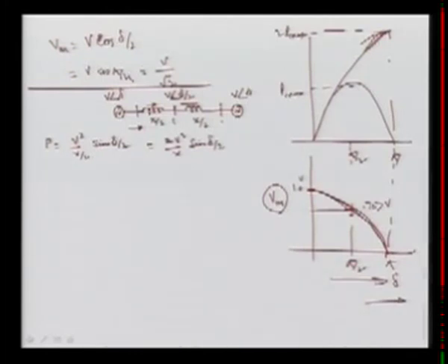So now this is the power flow, given by this expression. If we draw the characteristic, what is happening? If delta is 0, P is 0, we are here. If delta is pi by 2, then, putting pi by 4, 2V square upon X times 1 upon under root 2, we get under root 2 V square upon X, and we get some value here,